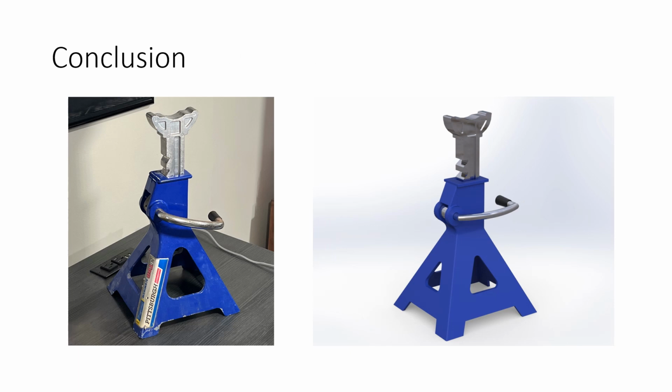Our results show that the jackstand would have to be significantly overloaded before it presents any safety risk. This is under the assumption that the jackstand is being used with a basic level of common sense. Further analysis could be performed to determine how the jackstand behaves under improper loading, or how it would be affected if it was shock loaded by a car being dropped on it. Ultimately, it appears that a large factor of safety was kept in mind while the manufacturer selected the 3-ton rating.